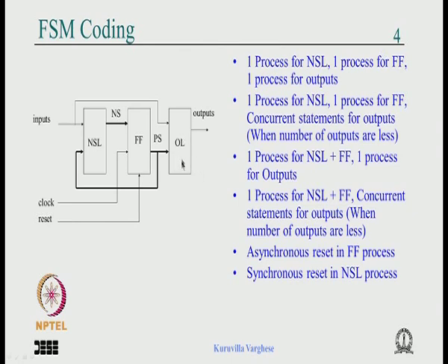Similarly for the Moore kind of output, you can say case present state is, or with select, whichever one you use. Again you can use if for the Mealy output under the case and so on, and this is a process where you use the if statement with the reset and clock event or rising edge clock for the flip flops.